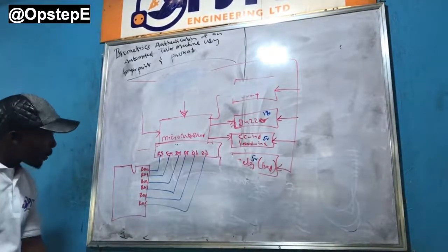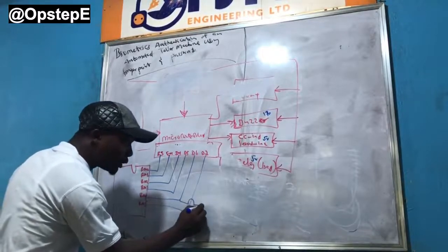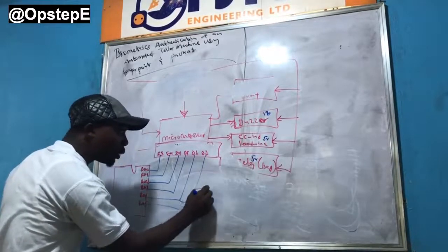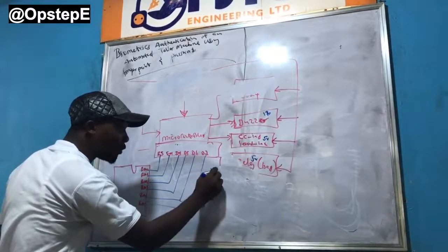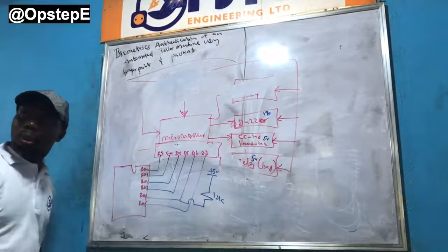So the pull-up we're talking about is on RA4. I can take here and put it through a resistor and take this to my plus 5 volts. This is a 10 kilo ohm resistor. This is the pull-up resistor. What are you talking about?